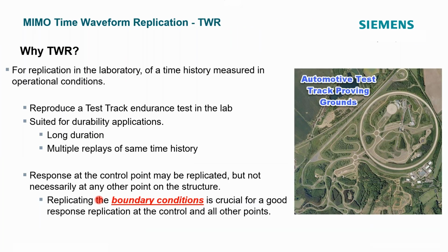The last case here is the time domain. The idea here is that this is typically for automotive applications where you want to drive around a test track maybe 1, 2, or 3 times and take some response information from your vehicle, and reduce that to something you can apply in a laboratory. So you want to take those time histories and replicate those in a laboratory. So we're going to do this in the time domain.